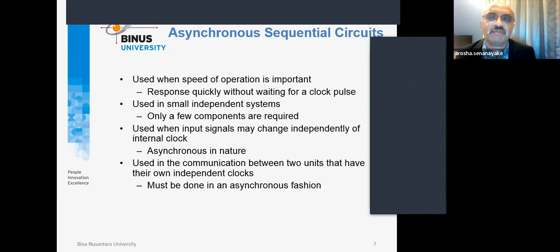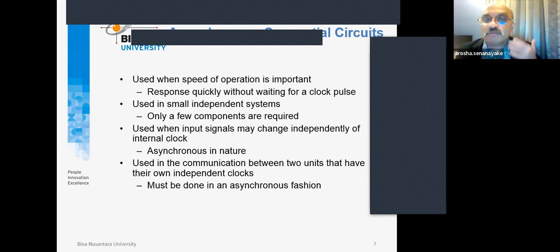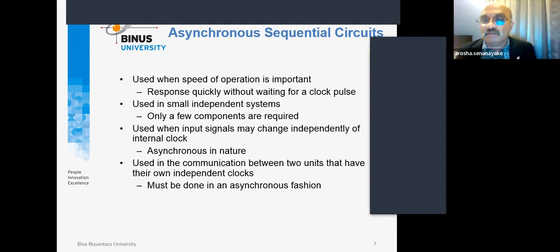The main reason, as I explained right at the beginning, is that the output of each logic gate, each circuit, requires some time to produce the output, and that delay might make the entire output meaningless. Sometimes an input variable is available, but unfortunately some other variables are not present, due to delays that occur.